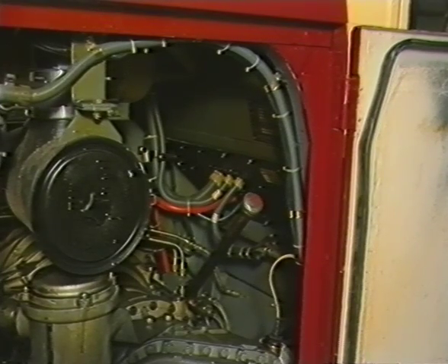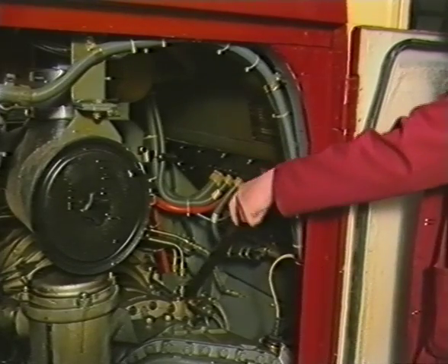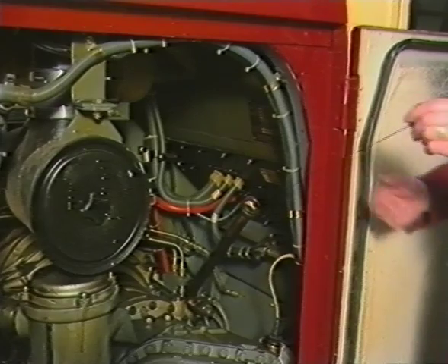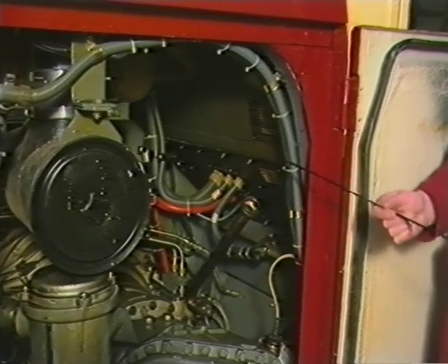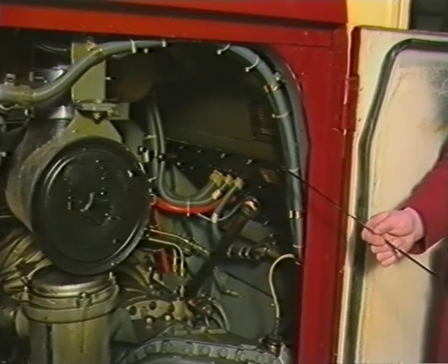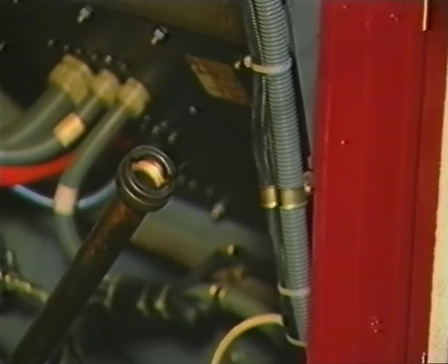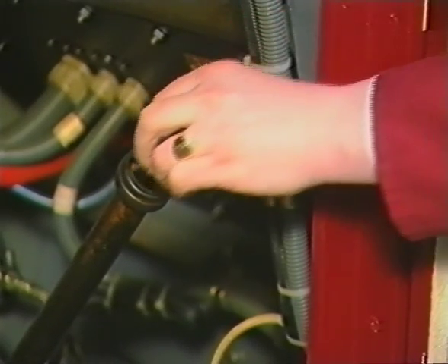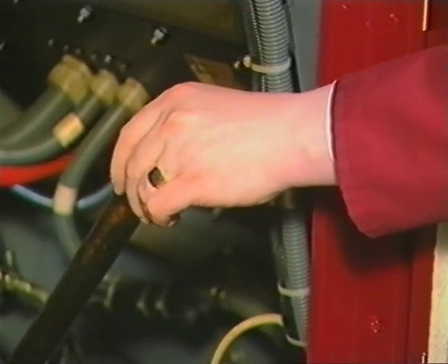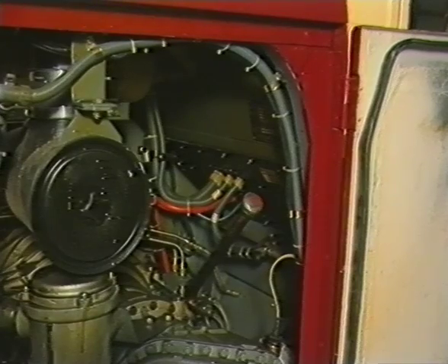The first item to inspect is the oil level. If the oil level is too high, this causes excessive churning of the oil by the gearbox running train, resulting in high oil temperatures. In instances of very low oil level, the gearbox clutches and converter may be in a partial slip condition, again causing an increase in running temperature. High oil temperature may also be created by using oil of the incorrect specification and viscosity.